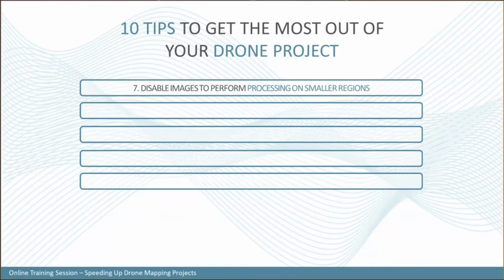It's something that's usually highly underestimated, but you can disable flight lines, images, and really set the overall areas of interest. A lot of times we have the question, how can I set up a processing extent of my project? Well, by disabling flight lines and images, this is a good way to achieve your desired section you want to process.